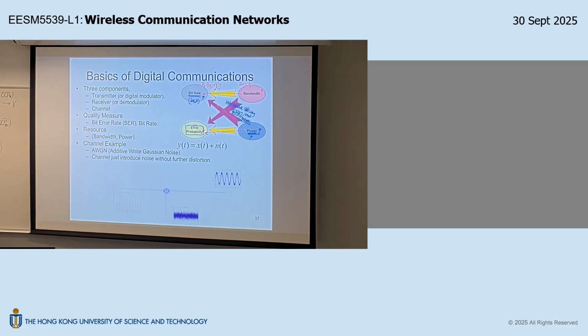Okay, just keep in mind there are two types of system. The noise limited system, where you can just control the signal-to-noise ratio by increasing the transmission power. The other type of system is called an interference limited system. For an interference limited system, you are pretty helpless. You cannot have too much control over the SINR received by the receivers. So you definitely cannot improve the performance by just naively increasing the transmission power.